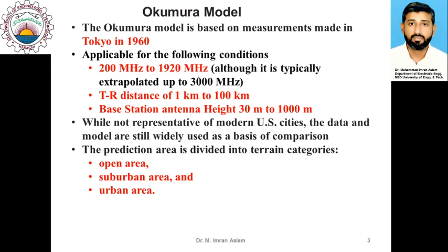The measurements that were carried out in this scheme were in the range 200 megahertz to 1920 megahertz, although we can extrapolate up to 3 gigahertz. But this is the actual distance range which was used in that model. Oh, sorry, not distance range, frequency range. So this was the actual frequency range that was used in that model, 200 megahertz to 1920 megahertz.